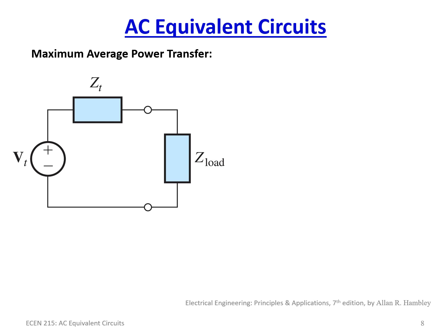So you actually get the maximum average power transfer in an AC equivalent circuit when Z load is equal to the complex conjugate of ZT. I won't go through the math on this. You can go back to the previous lecture topic on power and see that this is true. The maximum power transfer for Z load is when it is equal to ZT conjugate.